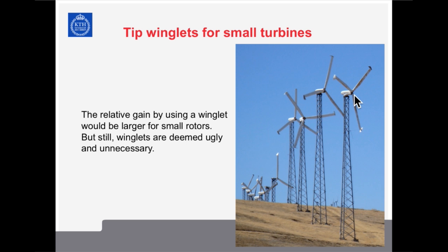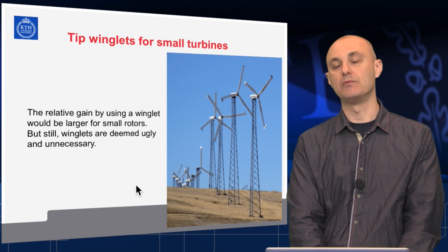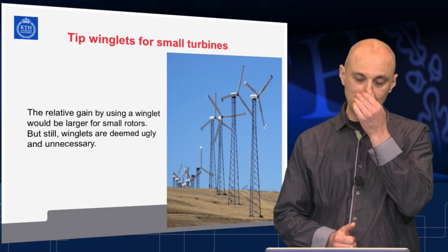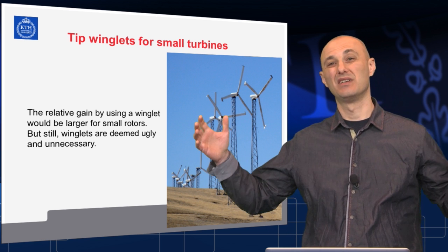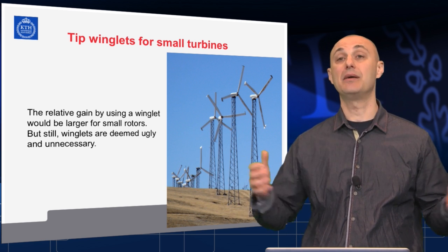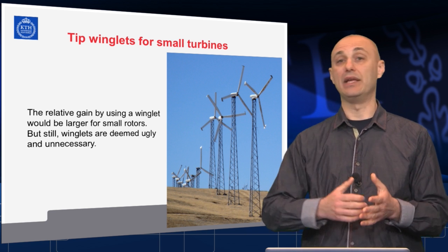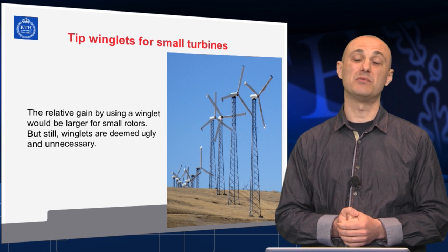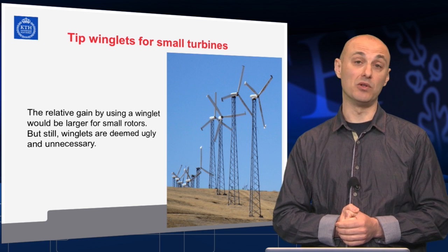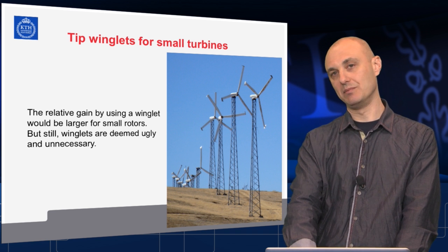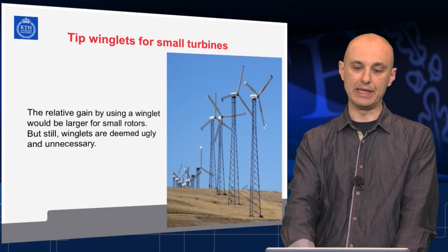It is actually quite rare, though, to see winglets on any wind turbine, especially in large modern, large rotor diameter machines. The size or the length of the blade actually shows that, well, the tip loss is relatively small. There's no point dealing with it. Rather, just having a simple, more solid blade is better.